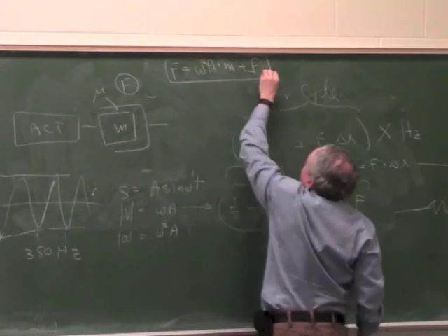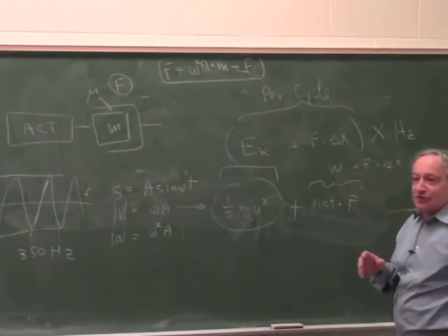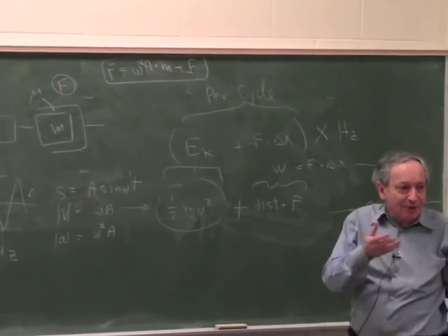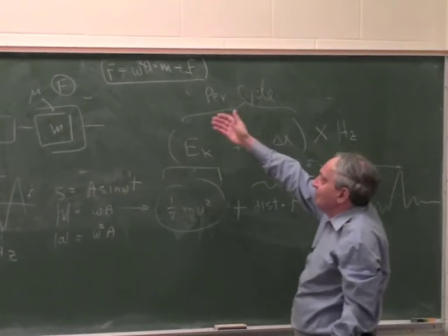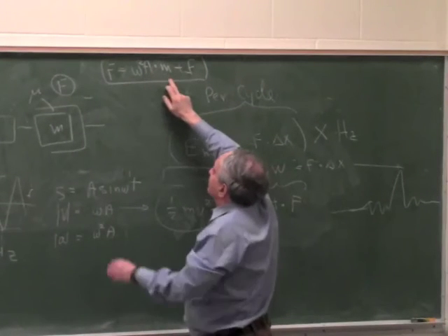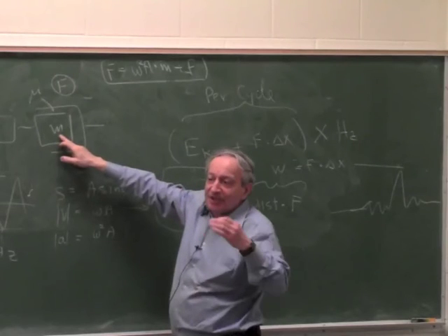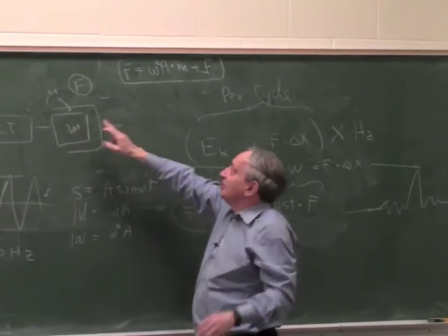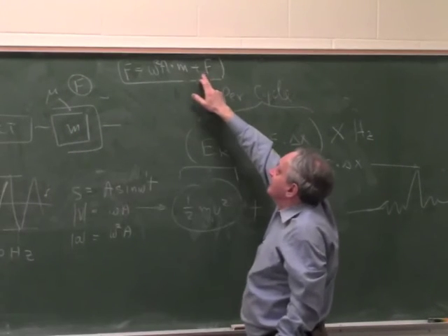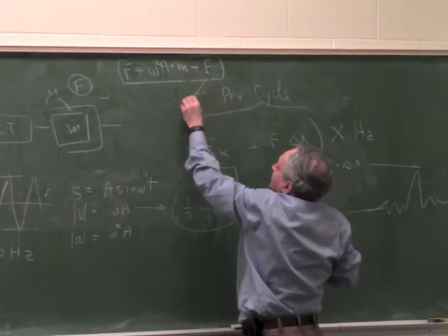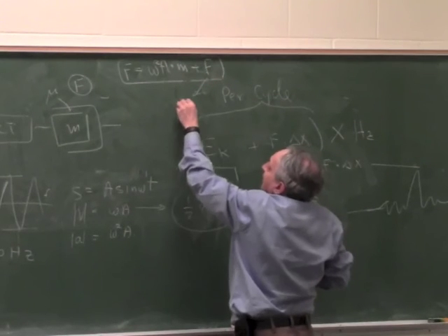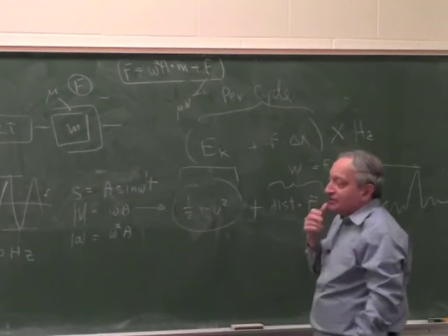So if you want to specify the actuator by force, not by power consumption or power output, it's even simpler. This is a force to accelerate the mass. It's a peak, a point of maximum acceleration, plus a constant force. And the constant force could be, for example, some mu n, a friction force, or any other force.